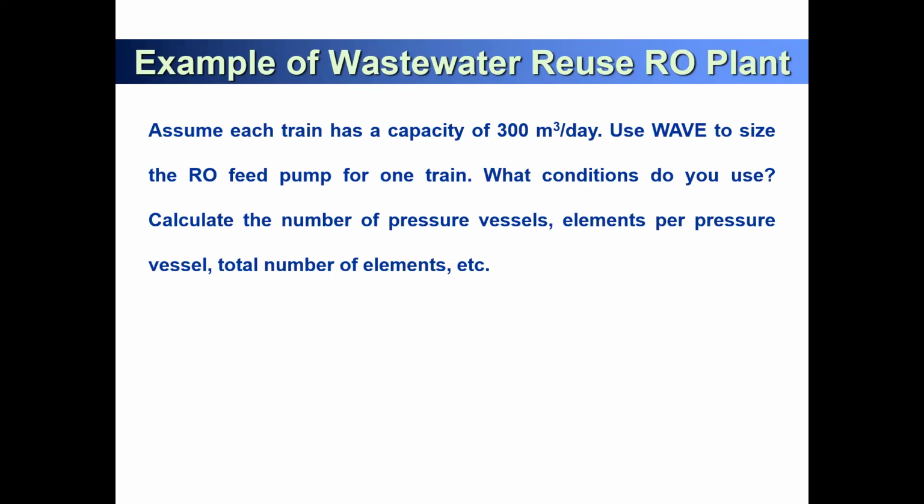So if you apply 100 bar, or even 70, 80, 90 bar, yesterday I showed the telescope-type damage of the reverse osmosis membrane module. We have to make sure of the best way to set our applied pressure, because you cannot continuously increase it. For seawater desalination, 60 bar, 70 bar, maximum 80 bar would be possible.